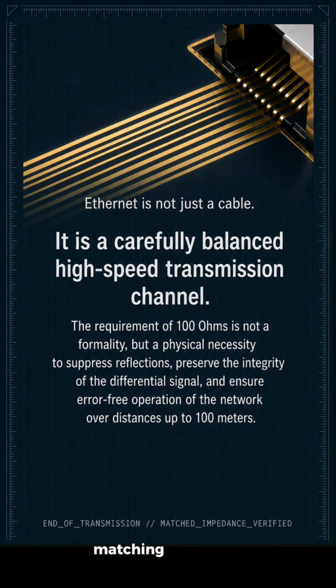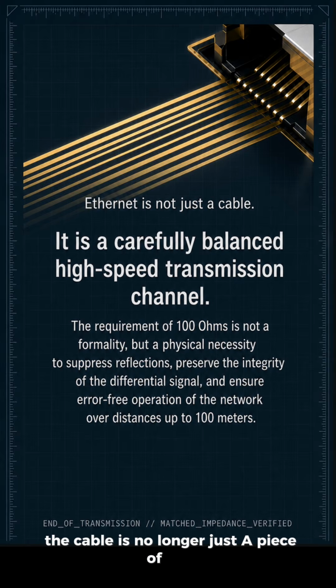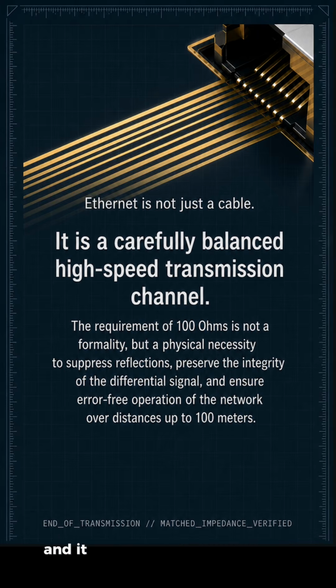Maintaining impedance matching in Ethernet isn't just a design recommendation, it's a fundamental requirement for ensuring that signals propagate through the entire channel without reflections. At Ethernet frequencies, the cable is no longer just a piece of wire. It becomes a true high-frequency transmission line, and it must be treated accordingly.